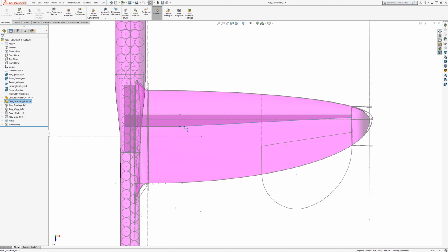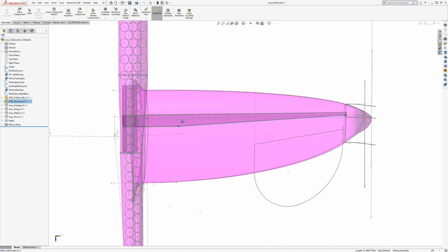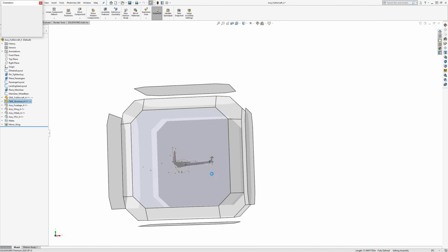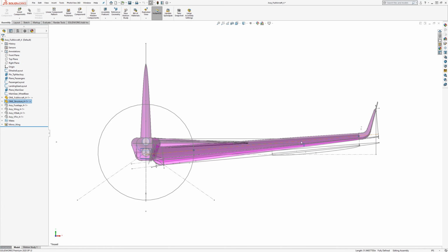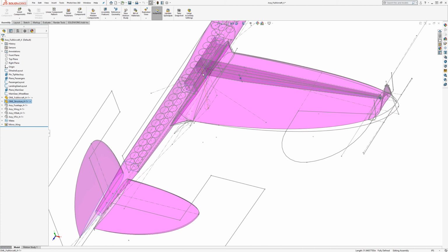You have an angle, in this case 3 degrees from perpendicular to its face, so 3 degrees here, plus the 5 degrees of the dihedral, and then that's meeting that, so that's 2 different angles meeting in one point. That's a complex meeting of geometry where you've got angles in 2 different planes both happening in one point.